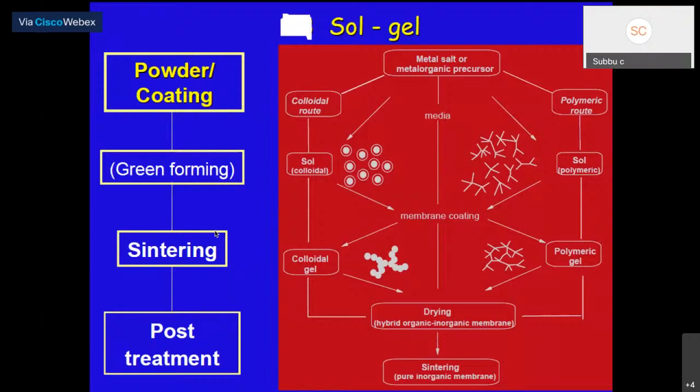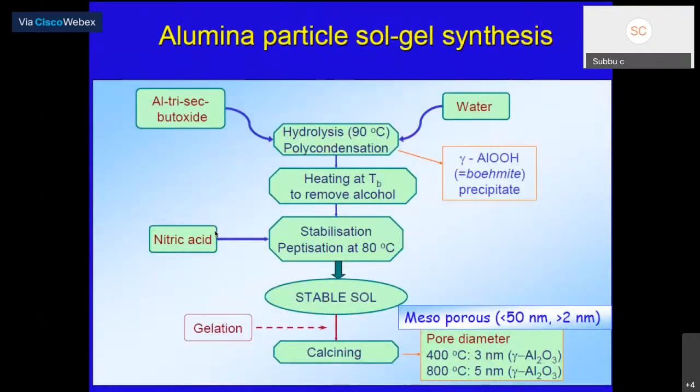Now, the controlled precipitation gives you a gel. A gel is nothing but water dispersed in a solid. Afterwards you try to remove the water by using some kind of heating called calcination. When you do this, you get the final product. That means you start with solutions, you prepare a gel, using the gel you build the network, and afterwards you remove the water to give you a final solid.